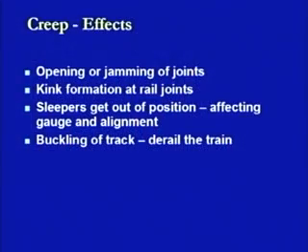Another aspect is that there can be buckling of the track. Now, when there is buckling of the track, it means the track is trying to buckle out in one direction because it has got jammed in one location, and the creep keeps on going, and there is no place where the rail can move out, then obviously it will start buckling in the outward direction.